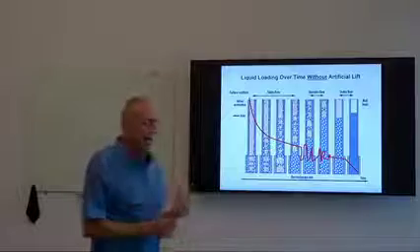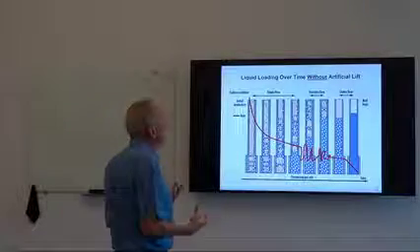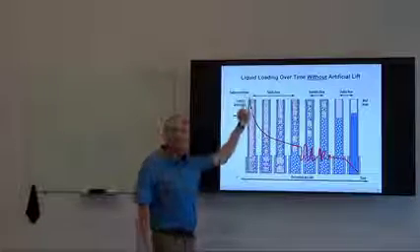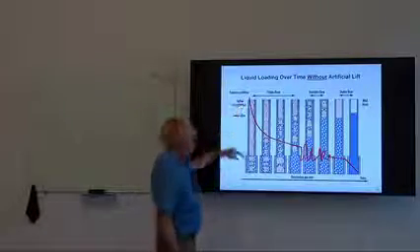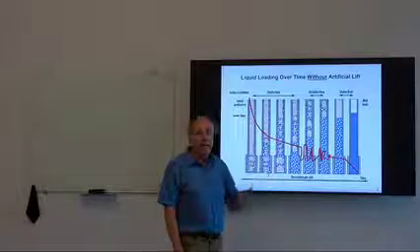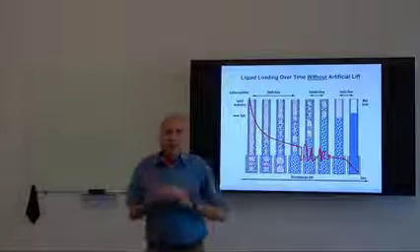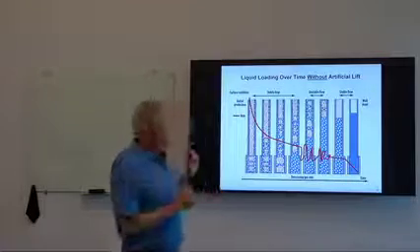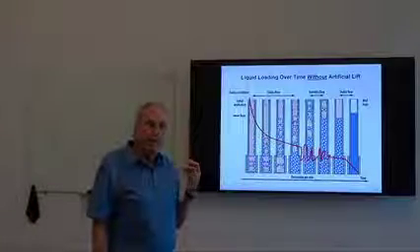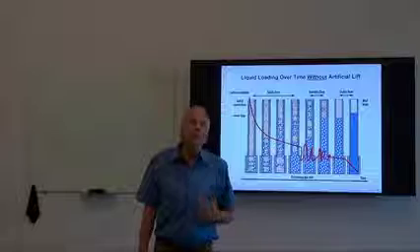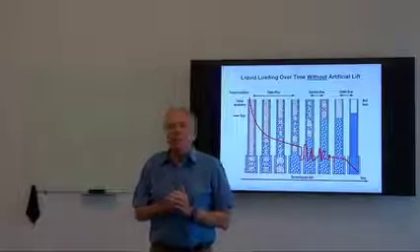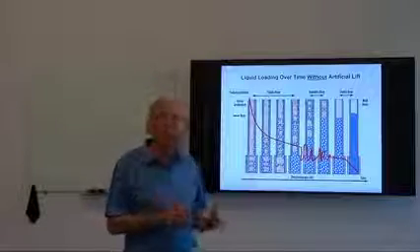But at any time in the life of the well, when we are free-flowing the well, and it could be after a plunger has risen to surface and taken all the liquid away even, where we're in afterflow and we have a high flow rate afterwards, we still have a reduction in rate through the rest of the cycle in which liquid will start to accumulate in the same fashion. So the onset and the progression of liquid loading looks the same in every case, whether in any free-flowing case over some period of time.